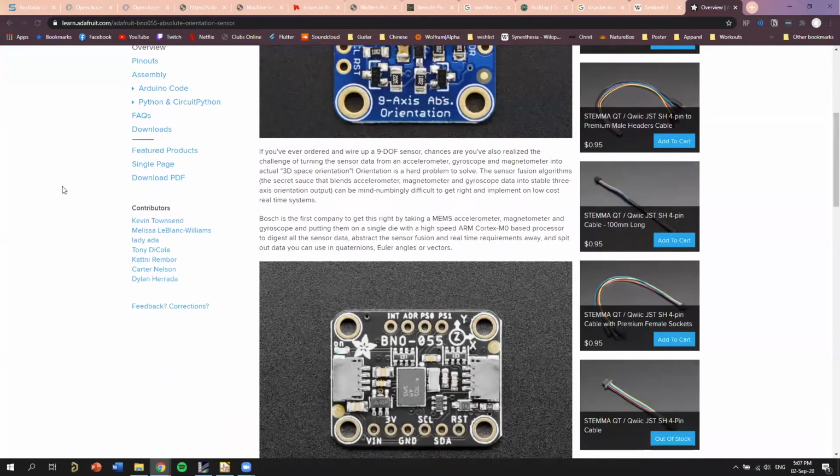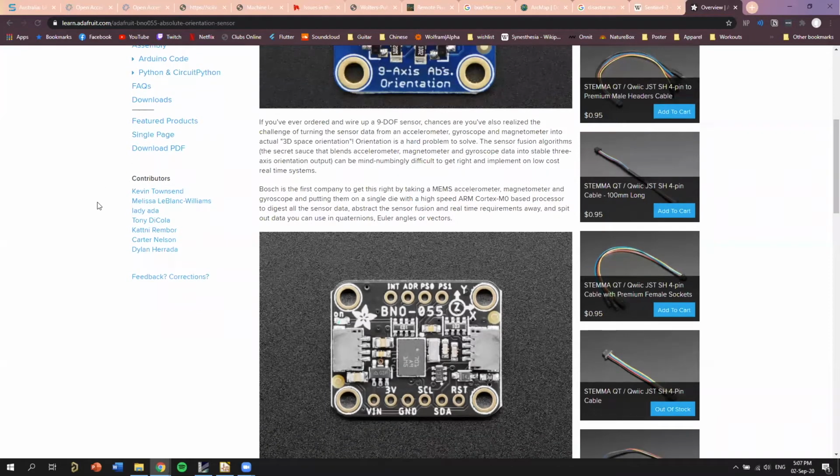Because if you're working with an analog accelerometer, it will just output a tiny little voltage that's proportional to the acceleration that's acting on it. And so, it might be that for every G that the accelerometer experiences in a certain axis, you get a couple millivolts change in the output of the sensor. And that can be hard to deal with, especially when there might be a lot of noise flickering around on that millivolt signal,